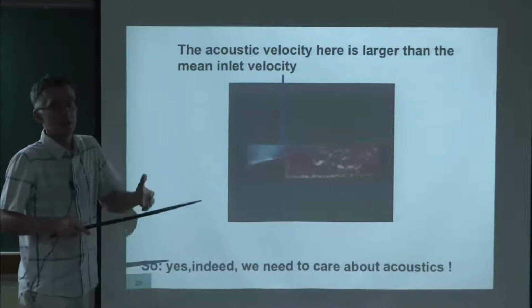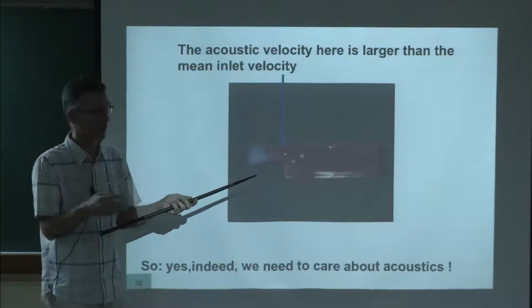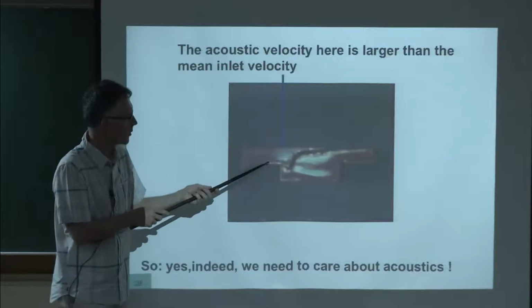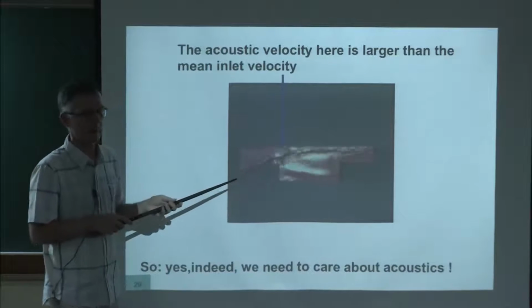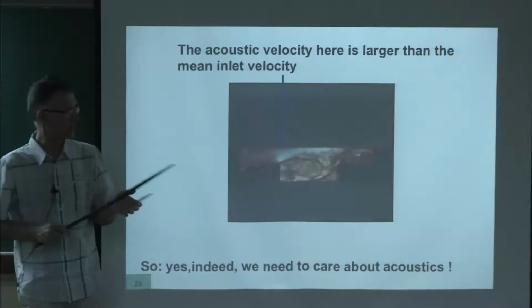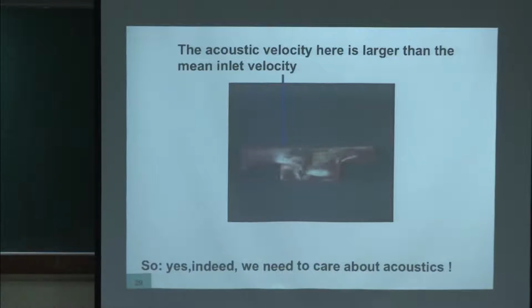It doesn't even have to be propagating. If the acoustic speed is 20 meters per second, the flame speed is only 20 centimeters per second. So it's not really propagating, it's carried away in the wrong direction. You can imagine when you design an engine that you don't want the inlet to be an outlet. It shouldn't go that way.